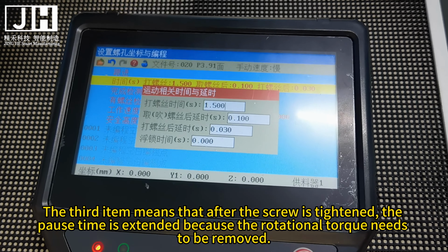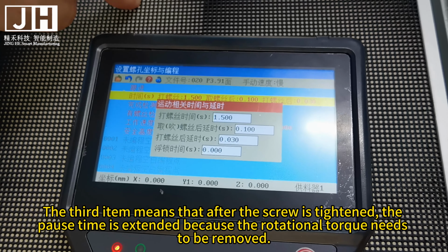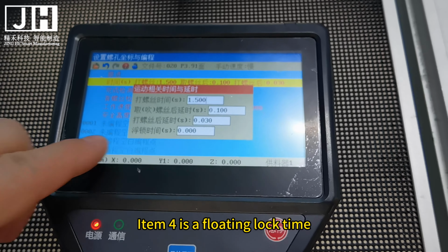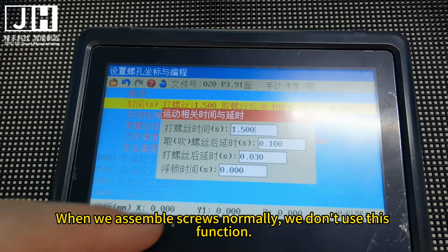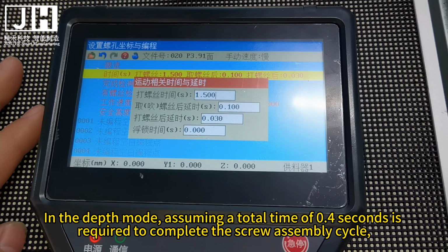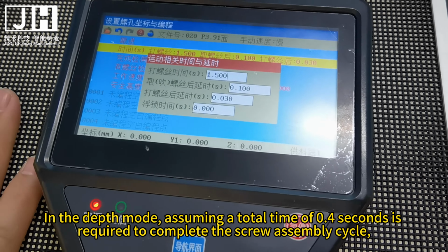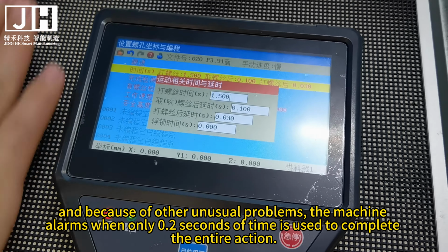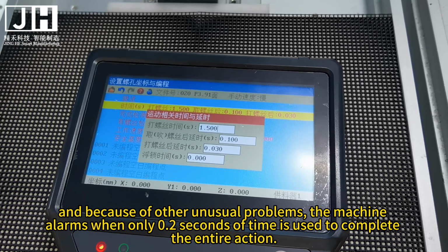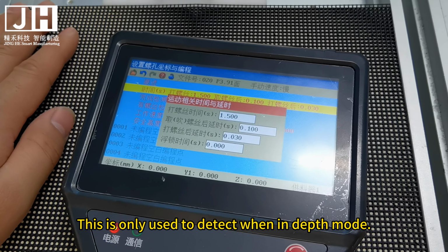The third item means that after the screw is tightened, the pause time is extended because the rotational torque needs to be removed. Item 4 is a floating lock time. When we assemble screws normally, we don't use this function. In the depth mode, assuming a total time of 0.4 seconds is required to complete the screw assembly cycle, and because of other unusual problems, the machine alarms when only 0.2 seconds of time is used to complete the entire action. This is only used to detect when in depth mode.